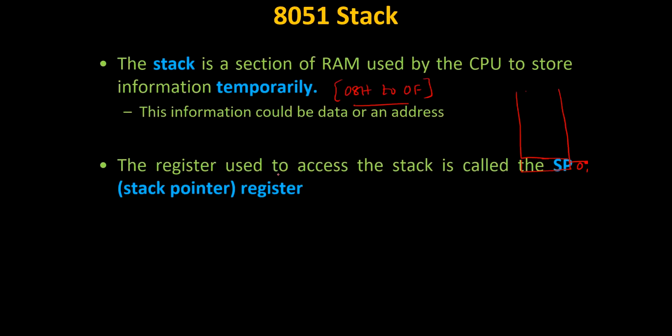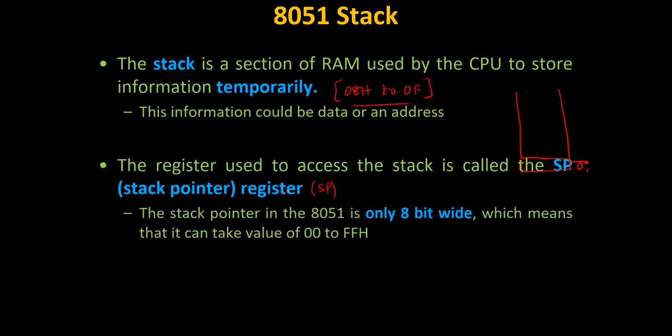The register used to access the stack is called the stack pointer register, that is SP. The stack pointer in the 8051 is only 8-bit wide, which means it can take a value from 00 to FF. So the size of the stack pointer is 8-bit.